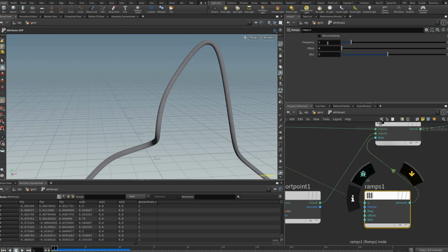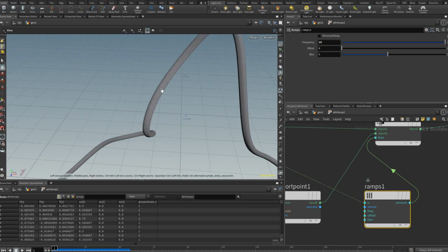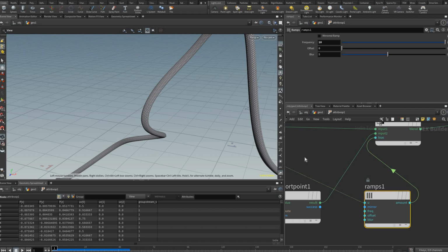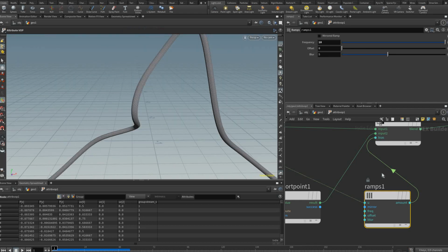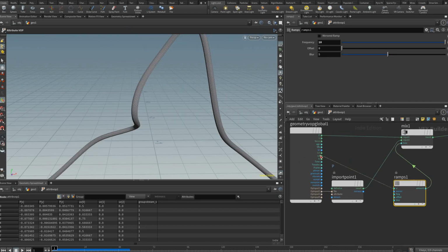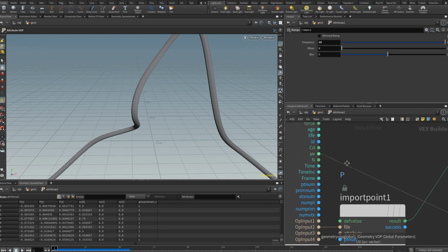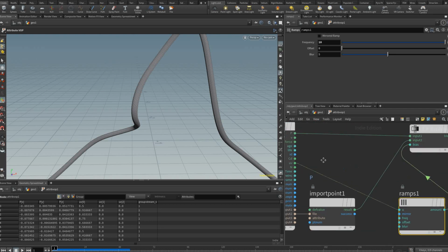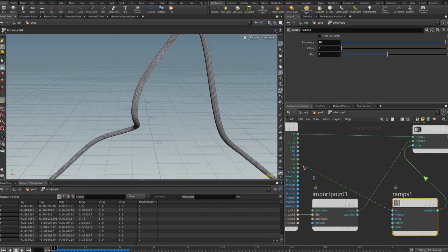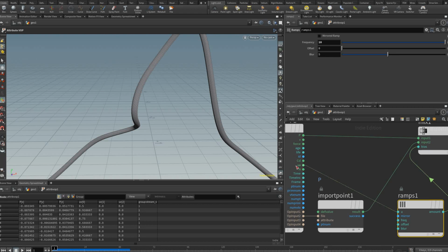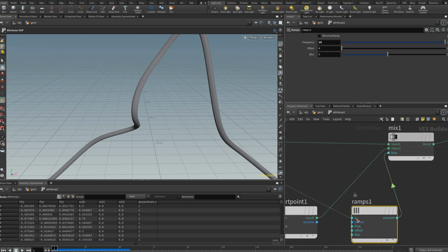And then frequency we could increase here, but as you can see, it's kind of picking a different direction than what I want. And the reason for that is because UVs are a vector, meaning they have 3 coordinates like x, y, z or u, v, w, and it's getting plugged into a value that's just u, that's just a float.